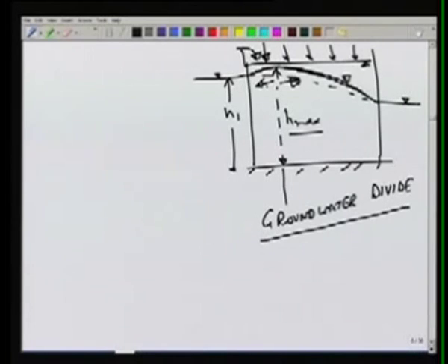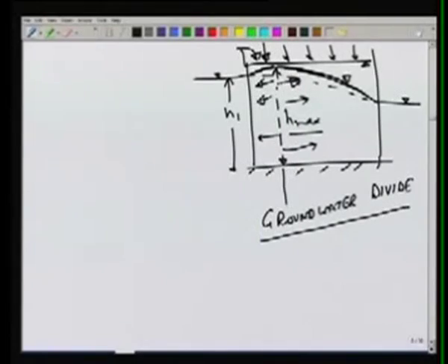So because of the presence of the gradient in this direction here and the gradient in this direction here, the groundwater will flow towards one side, so this side, and towards this side. So this line can be thought of as dividing the groundwater such that one part flows into one water body and the other in the other water body. We can find out the location of this point also. For example, the Q value is known to us.